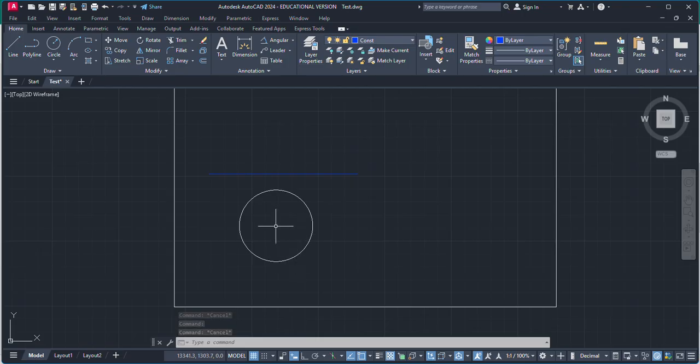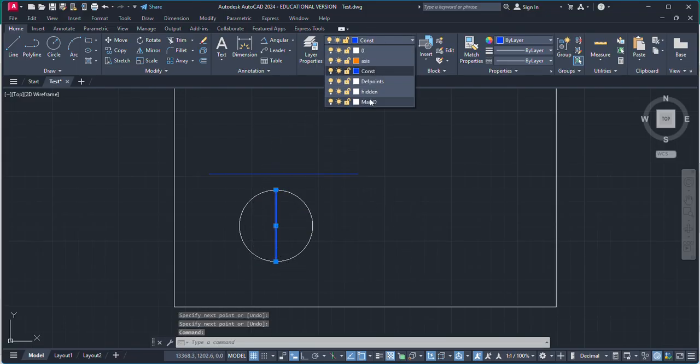Again we will have a top point here, but here, if we have a circular profile, then to trace it very precisely, we divide this circular part into minimum 8 equal parts. 8 equal parts are good enough to trace this curved profile. So I'm going to first divide this circle into 8 equal parts. Just change this to the main drawing.